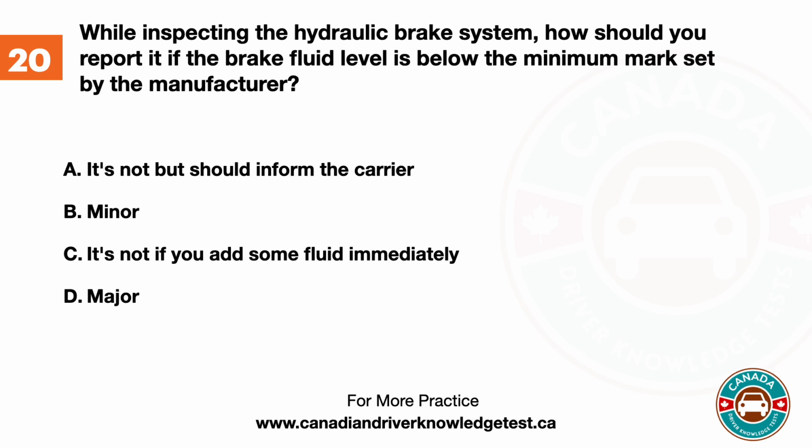Question 20. While inspecting the hydraulic brake system, how should you report it if the brake fluid level is below the minimum mark set by the manufacturer? A. It's not a defect but you should inform the carrier. B. Minor. C. It's not a defect if you add some fluid immediately. D. Major. The answer is B.